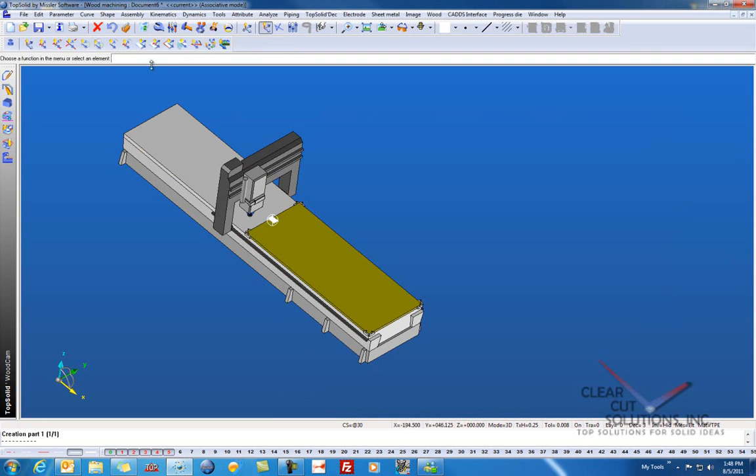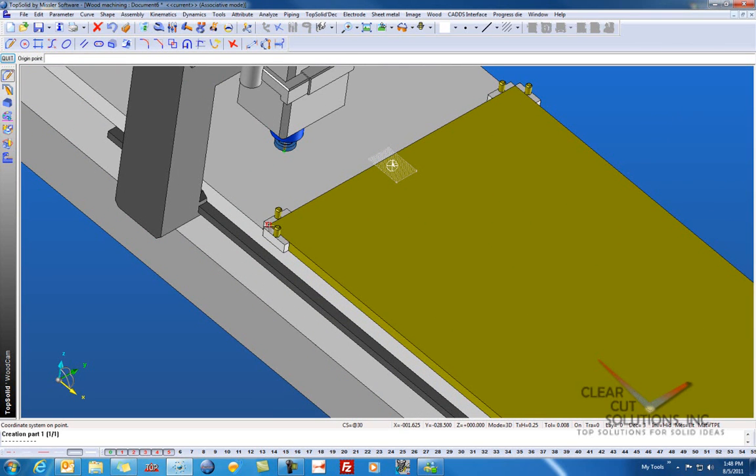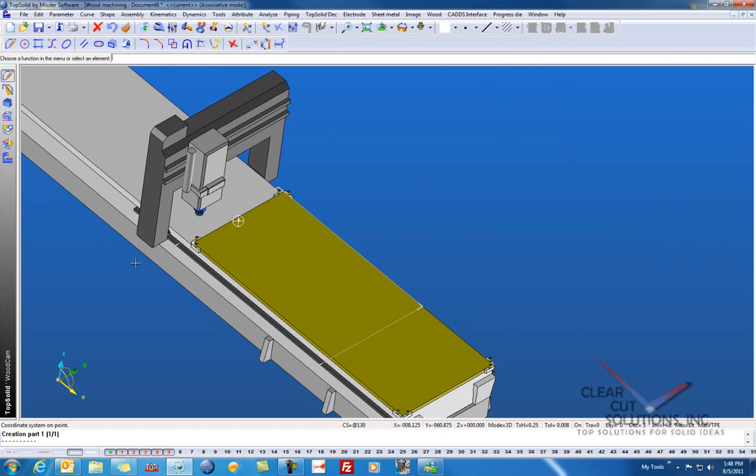So for example, if I go and create a new coordinate system here, and I just put it right there, and I set it current, you can see that the border here has gotten quite big. And what that's going to allow us to do then is, when I go to create a sketch line, have a very large sketch line to deal with. Okay? Perfect. So I'm going to switch back to the absolute.